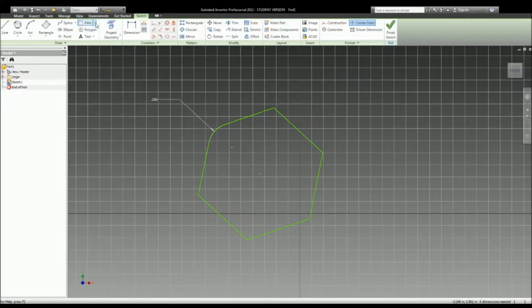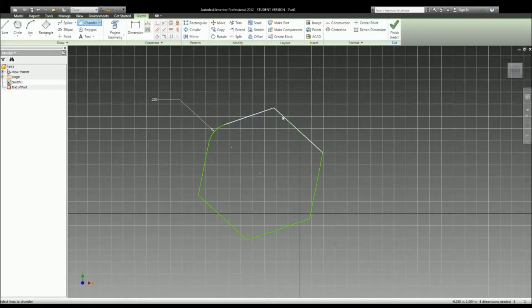Okay. So I'm going to go to chamfer, and there's three options for chamfer. First, I'm going to just start with the original. Right now, the distance is 0.125, okay? Chamfer, as you can see from the shape, it's D and D if you look closely. And what that means is this distance is how far it'll go in on each side. So if I click here and click here, it'll cut in 0.125 from the corner straight in. And then the diagonal is the resulting chamfer, right?